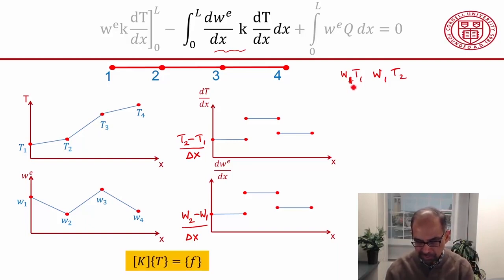And when you look at the stiffness matrix form of it, what this means is these terms will go into appropriate rows and columns of the stiffness matrix. So you have to do the bookkeeping, like, okay, this term, whatever coefficient I have here will go into the first row of the stiffness matrix. Which means that this term affects the stiffness matrix, whereas these two terms affect the force vector on the right-hand side.